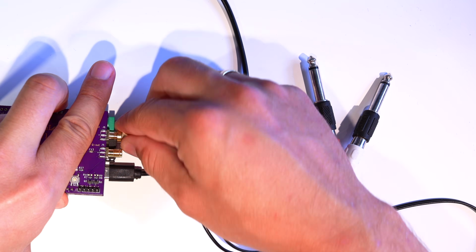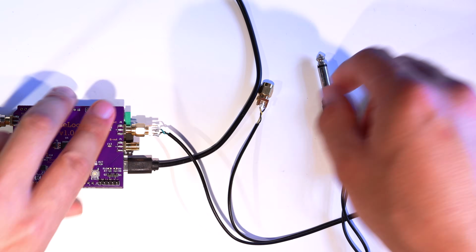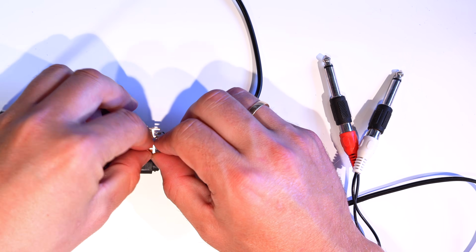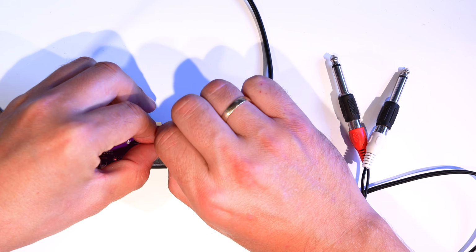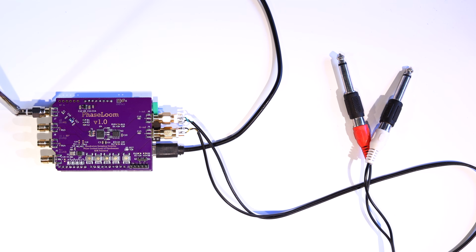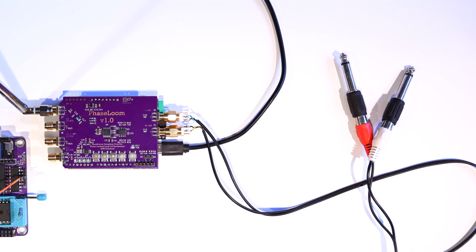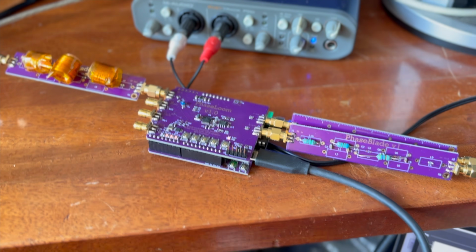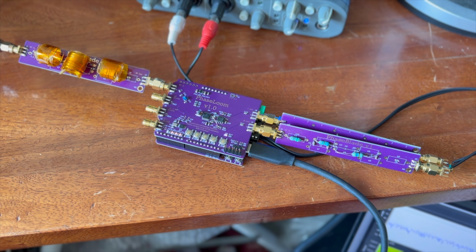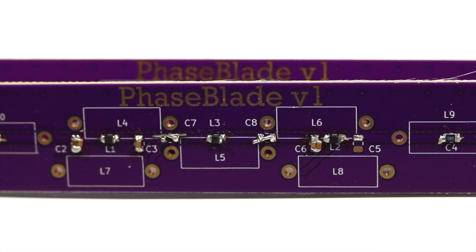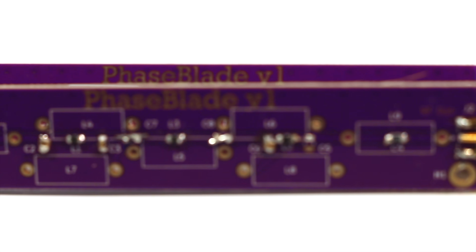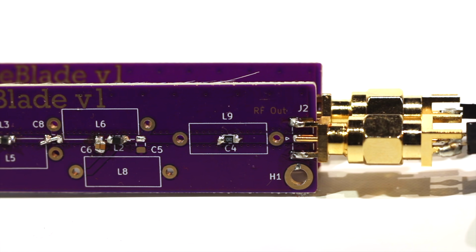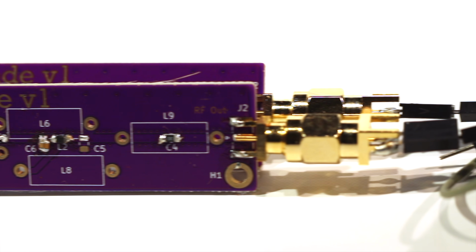Since my little 6502 platform, the 6501, doesn't have much of an ADC to digitize the incoming analog data, at the moment anyway, last time I chose to do what you'd do 25 years ago. Feed it to a beefier computer through the best ADC most people had, the sound card. In 2025, that just about makes it the worst bandwidth you can get out of an SDR on the market, since we're limited by the 44.1 kHz of the sound card. That's about 72 times less than the common RTL SDR can handle, and not even enough to decode FM radio.